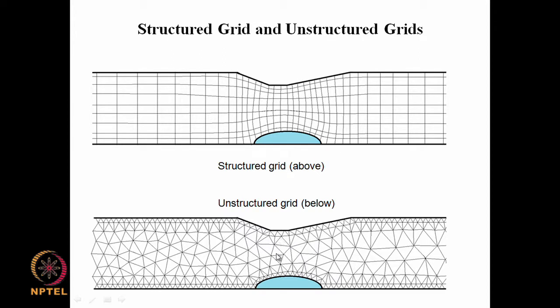So, in that sense the number of neighbors is not fixed in this unstructured grid. But whether you do the discretization on the structured grid or on the unstructured grid, we still end up with an equation like A phi = b, which we have seen. And in the case of structured grid in 2D here, for the diffusion equation, the Laplace or Poisson equation, we will have the 4 immediate neighbors. That is, for point ij we have i+1,j, i,j+1, i,j-1 and i-1,j.